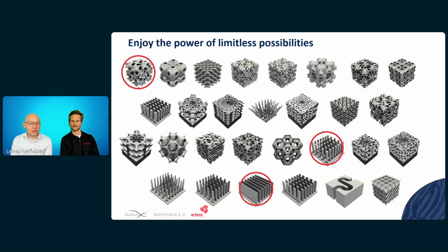This choice is obviously not random, because the skived fins have the property of maximizing contact area, which triggers certain coolant flow modes and pushes more towards the laminar flow regime, while pins trigger turbulence more easily, and these gyroid shapes have a high mixing effect.